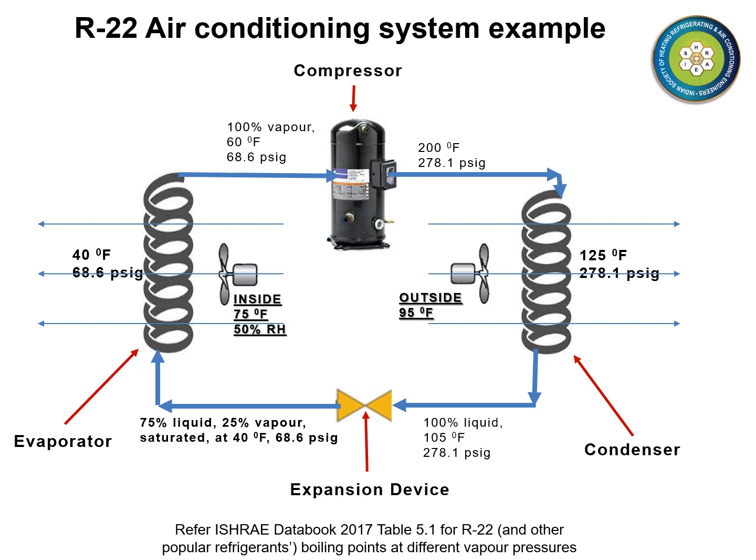You will find the boiling points of R22 as well as of a few other popular refrigerants at different vapor pressures in table 5.1 of ISHRAE Databook 2017. Notice that the R22 entering the evaporator is 75% liquid and 25% saturated vapor at 40 degrees Fahrenheit and 68.6 psig vapor pressure.